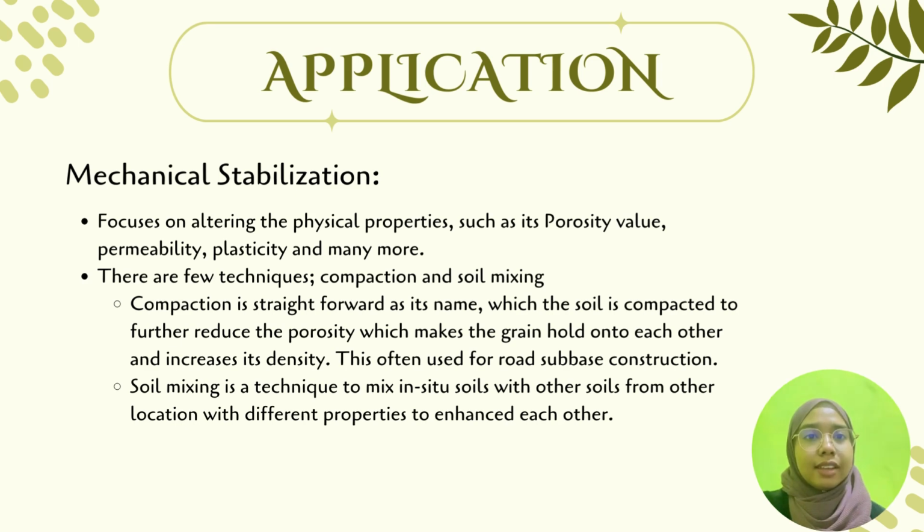The second technique is soil mixing. Soil mixing is a technique to mix in situ soils with other soils from other locations with different properties to enhance each other. So that means the soil is combined with two or more soils of various grades together. For non-binding cohesive soils, they add an amount of fine materials such as clay or silts.